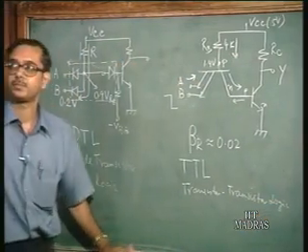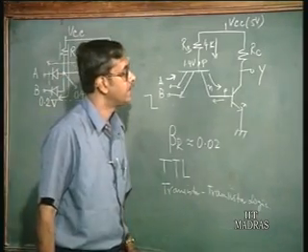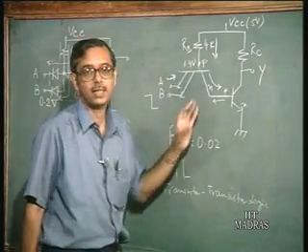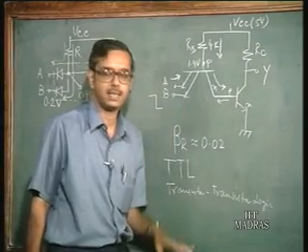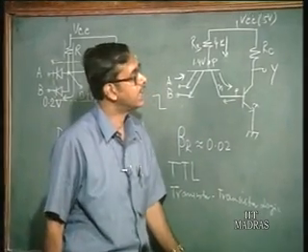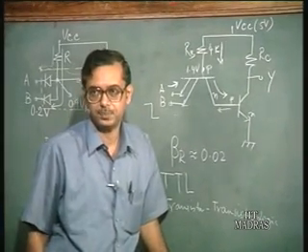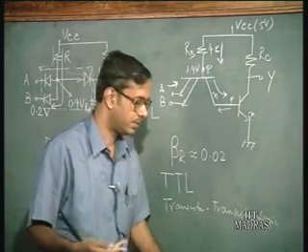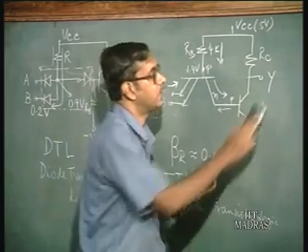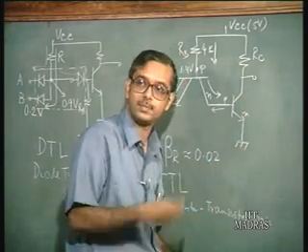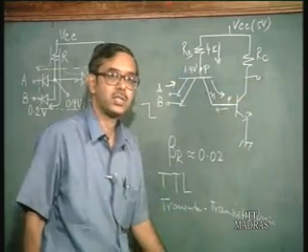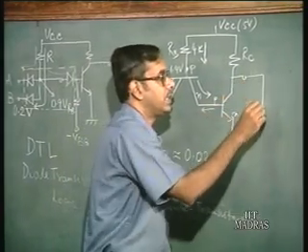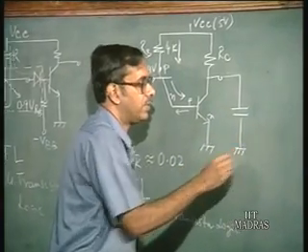All right. Well, so we know that this circuit now behaves as a NAND gate and is much better than the previous DTL circuit. But again, this circuit has its share of problems, or I mean everything has its problems, but we have to look at ways how to improve it. So, most of the delay associated with this circuit is, suppose this circuit is driving a capacitive load.